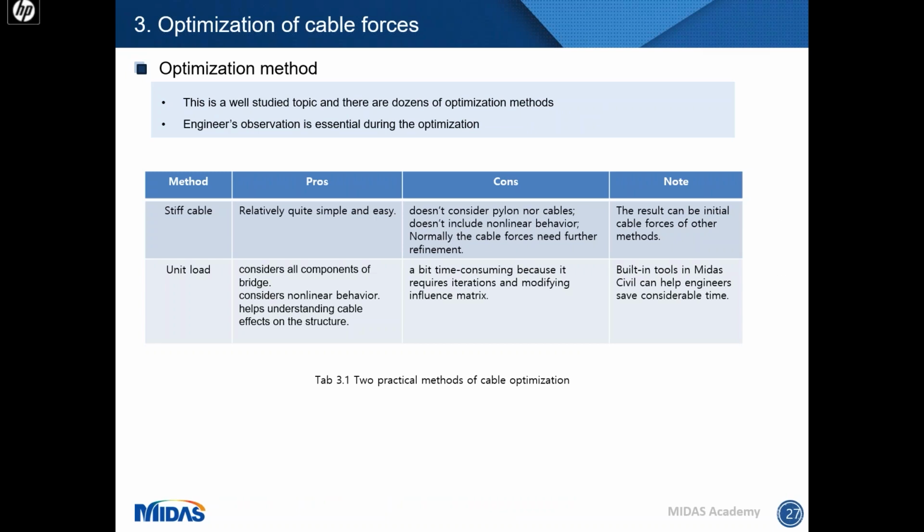For the optimization method, actually, this is a well-studied topic, and if you search online, you will find lots of papers on it and dozens of optimization methods. Today I want to mention two of them. One is the stiff cable method, another is the unit load method.